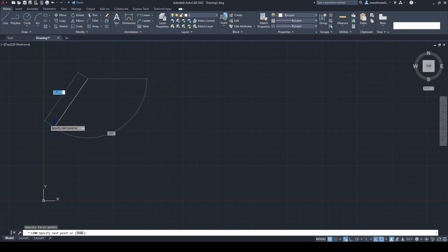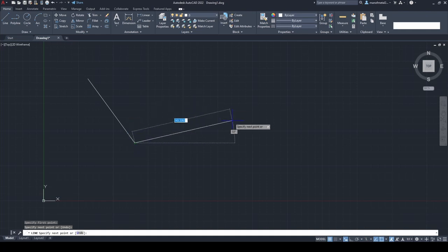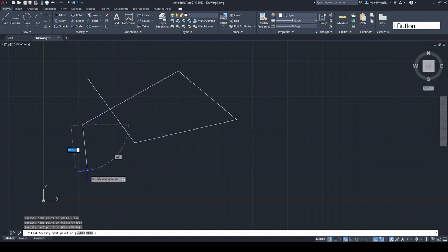When I'm happy with where the line is, I click again to decide that this is what I want my line to be. If I have a specific measurement in mind, I can also input it into the number pad and press enter, and I get that measurement. Of course, I can just click randomly wherever I want and continue on making the shape I like.